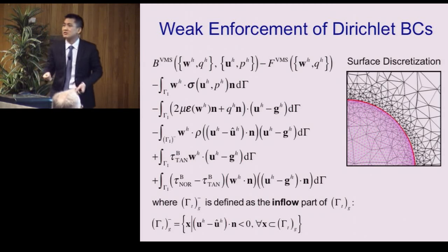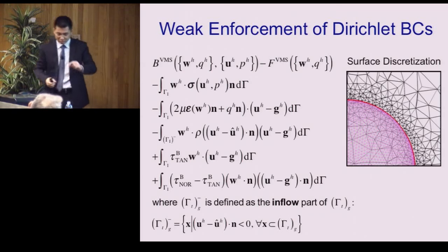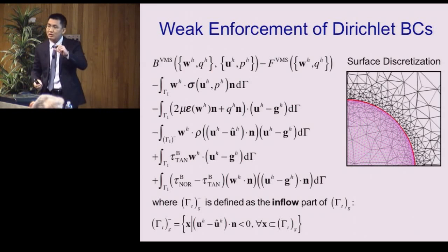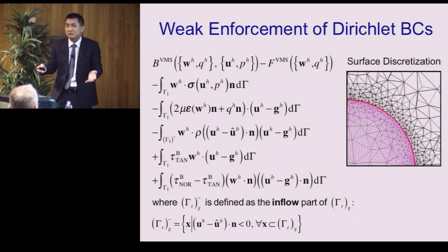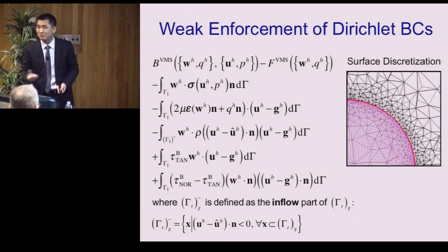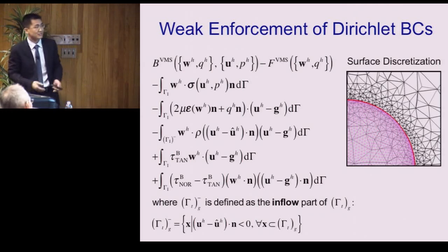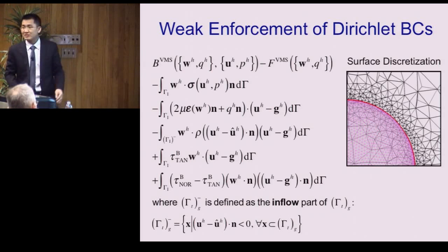And what this allows is the flow to slip a little bit on the surface. So even though you have a little bit coarse resolution of your boundary layer, you are still able to resolve the flow field in the interior. And of course, you're not able to resolve the boundary layer completely. But because of this release of the constraint, you don't have to resolve the boundary layers to get the accurate result. But that was what happened back then. In this case, we just apply directly for this immersed type approach. And this is how we impose the boundary condition.